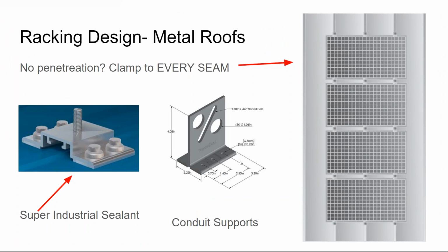So then we get to standing seam, and kind of the number one mistake I see is installers go with that 4-foot spacing that they're used to with positive penetrations, and they apply it to standing seam, whereas really on a standing seam rooftop, you want to go with a railless system where there's no rail underneath the module. That gets the panels closer to the roof line so they catch less wind underneath the rooftop. And then you have a clipping system.